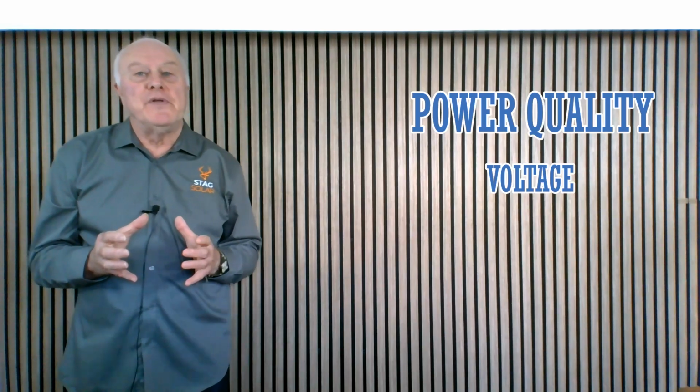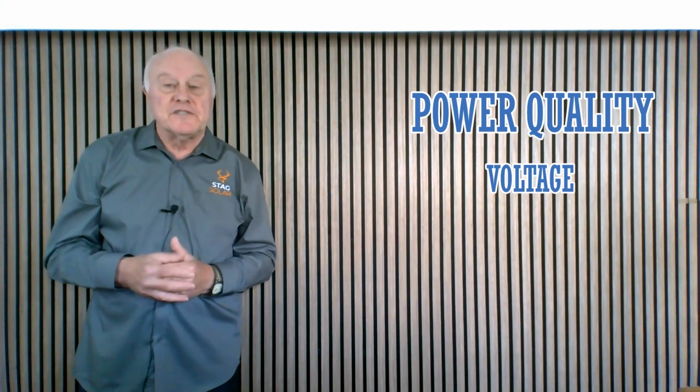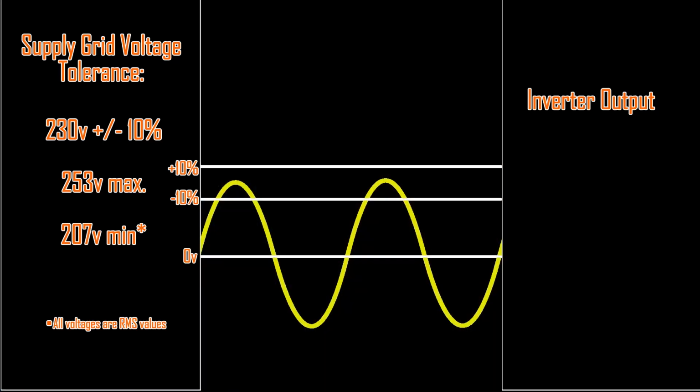For example, we have to ensure that the voltage output at the inverter output terminals does not exceed set limits. As you can see here, the grid voltage is allowed a plus or minus 10% tolerance, and once synchronized, these limits must be maintained. Now, it's actually normal for inverters to cause a certain amount of voltage rise, but once this reaches the limit, the inverter immediately shuts down, and the same would happen if the voltage fell too low.